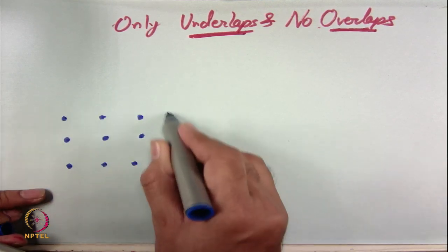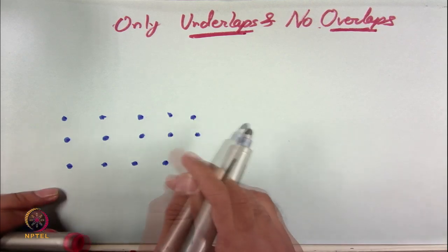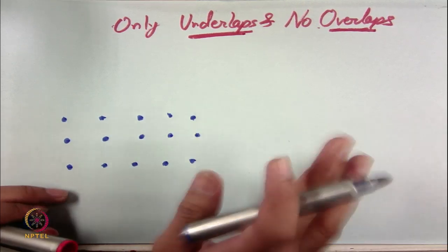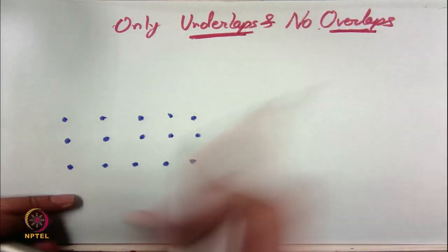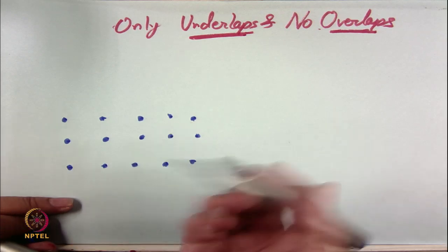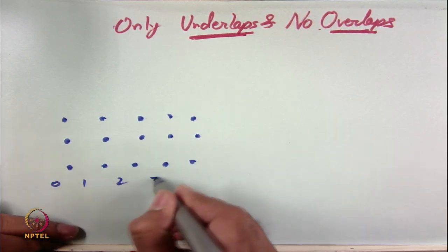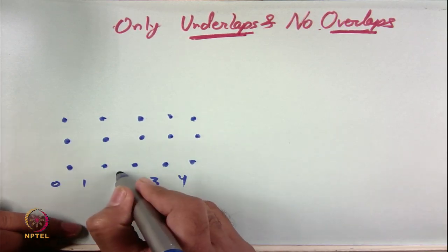So, it means the yarn is just floating, it is not being provided to the needle. So, the needle is not making any loop at all if the guide bar is doing this. So, it is just floating at the back side. Let us suppose we started from any position, let us suppose I start from second position.